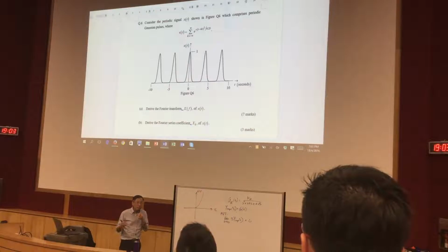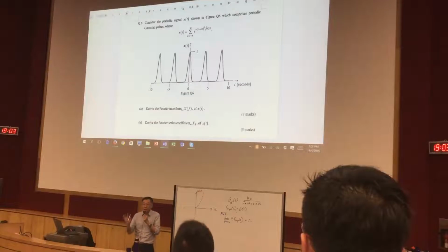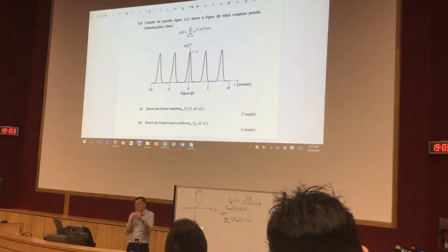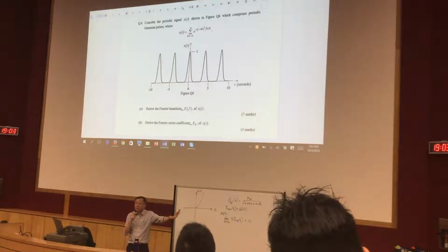How? Remember, always decouple this into the generating function, that means 1 pulse only. Now convolve with your comb function to get the periodic signal. Got it?